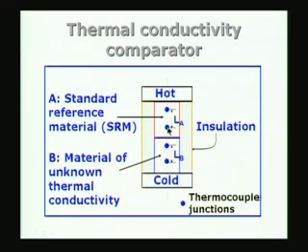In practice, they are going to be very thin junctions, very small junctions. They may not be embedded inside the solid, it may be at the surface if necessary. It is easier to attach at the surface and measure the temperature. You need not drill a hole, otherwise you will have to do that, and of course, drilling a hole will probably change the heat transfer pattern slightly. So, that is also not a very desirable thing.